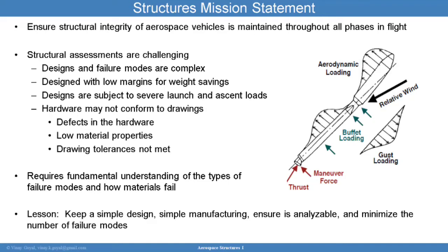But as the design matures, it's of high importance to start refining those models with high fidelity models, also called finite elements, to start to reduce mass, but yet make sure that I haven't reduced it to the point that I cannot accommodate defects in the hardware, and I cannot accommodate drawing tolerances. So it's very important, as a designer, to carry additional margins in your pocket. I don't want to design something with no margin. I want to design something with some margin.